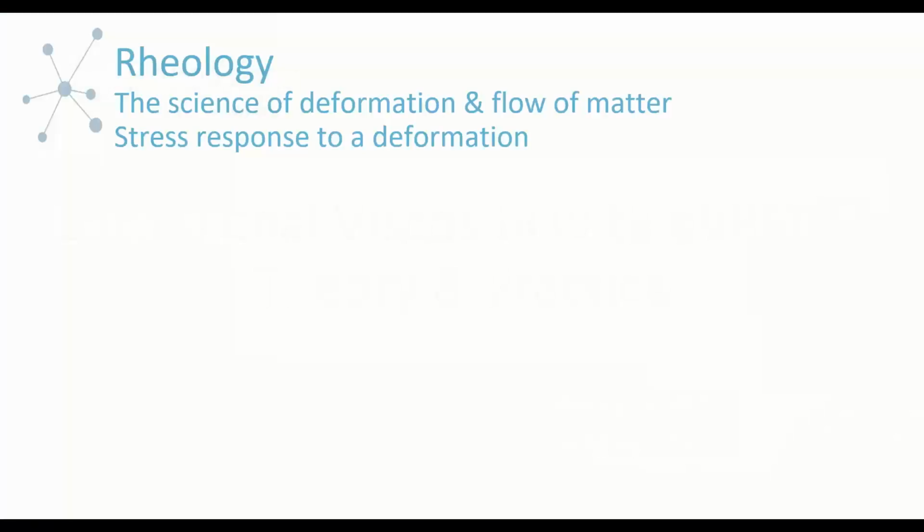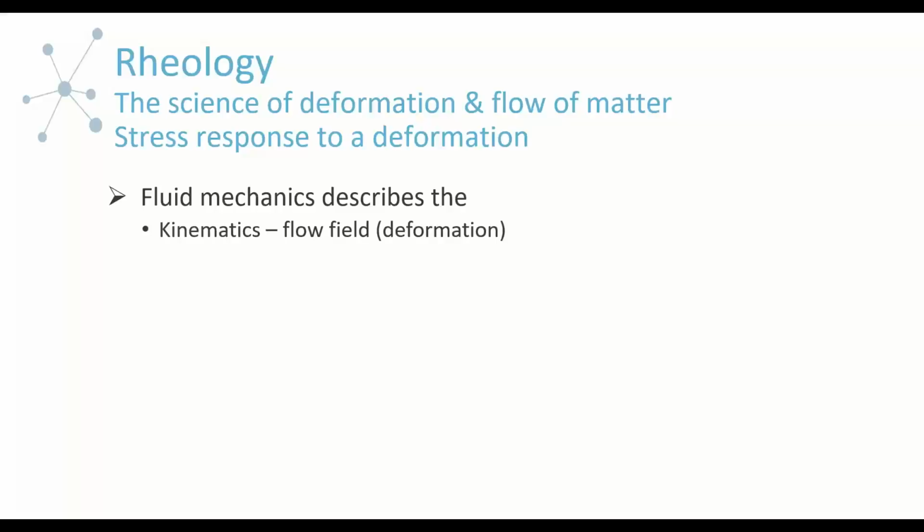So I wanted to start off, just so everything that I present today has a clear context, with the basic thought behind rheology and what it is. Rheology is looking at the science of deformation and flow of materials. An equivalent definition is to think of what is the stress response that comes from a particular applied deformation. And we use fluid mechanics when we deal with rheology because we need to describe two things. We need to describe what is referred to as the kinematics, which is the flow field or the deformation, and then also the dynamics, which is the term we use for the stress distribution.